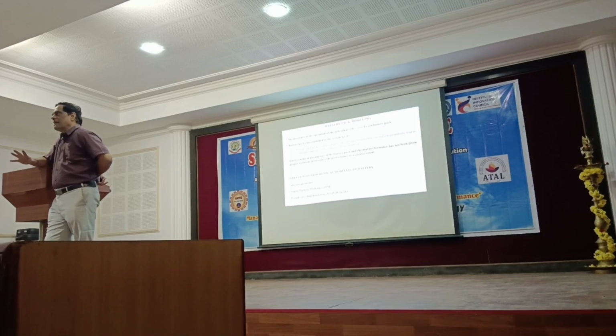We are translating the battery response in terms of whether they are conducting or resisting. We try to mimic the response of the cell or battery pack in terms of equivalent electrical circuit elements. Depending upon how they are arranged, series, parallel, series configuration, by constructing an equivalent electrical circuit model, for a given input current, what is the output voltage you are going to get from the cell?